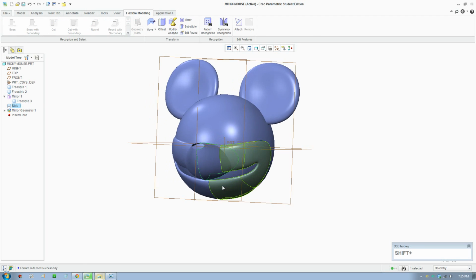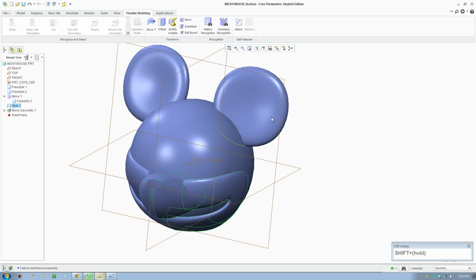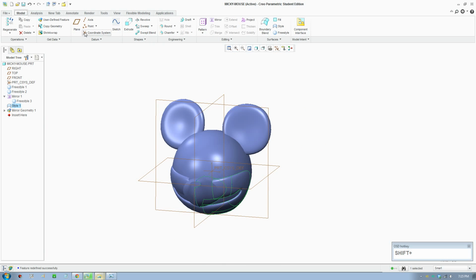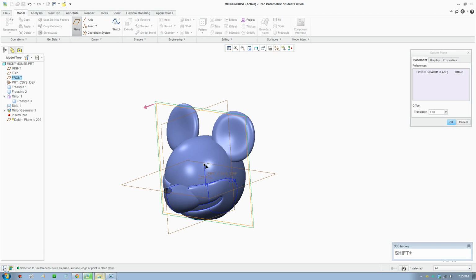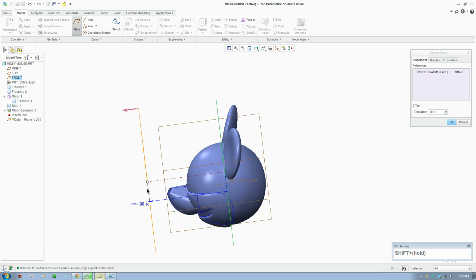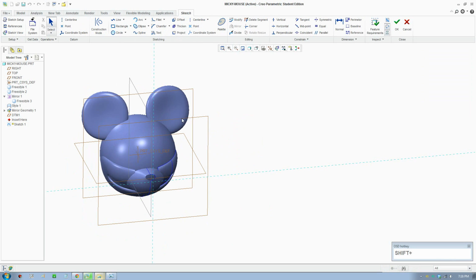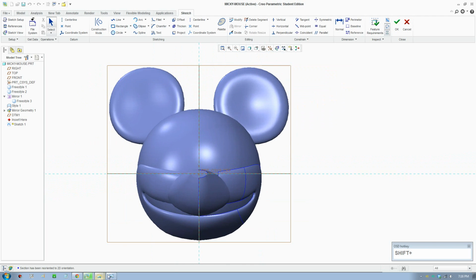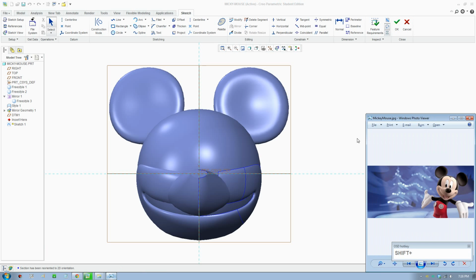Okay, the next step, we'll start to define the eyes. We're gonna work on the eyes. Okay, so for the eyes, go to plane. We're gonna click that plane and drag this button, the little square, that white square there, drag it forward, and we'll go to sketch. We'll create a sketch on that plane. Click that button to bring it forward, and find a reference picture of the face.